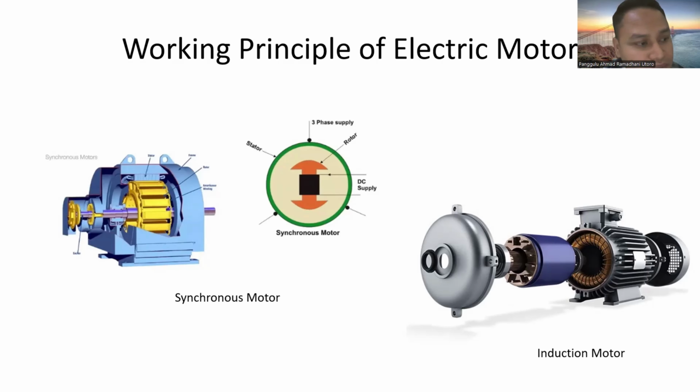Induction motors operate slower than synchronous motor speed and require power only to the stator, while synchronous motors operate at their synchronous speed and require DC power to the rotor for excitation, making them more complex and of course more expensive.